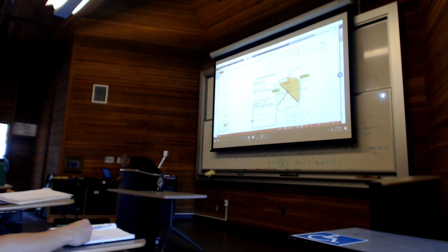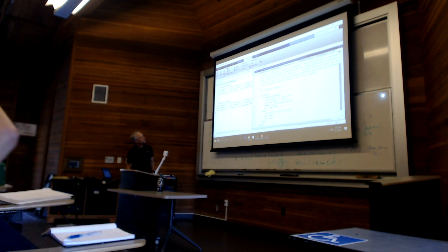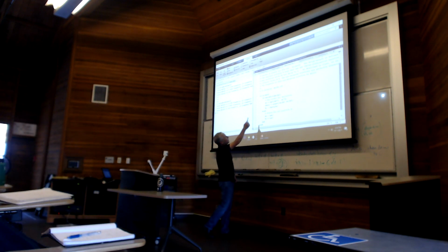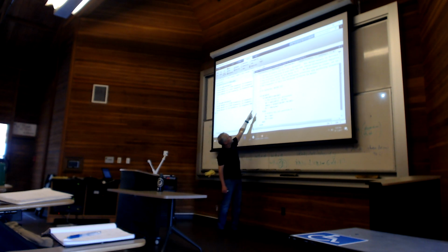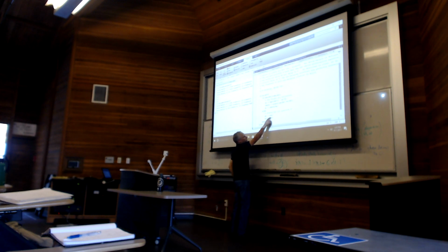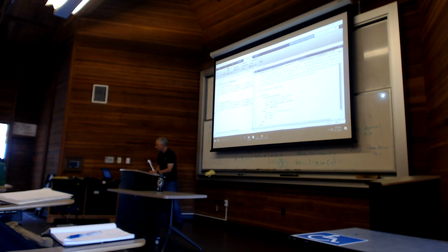So the code is delay margin calc. It's posted for you. We give it A1 and A2. I check if the absolute value condition fails, fine. Otherwise we'll print an error that says system is not stable at t equals 0. If A2 is greater than A1, like we're supposed to, we calculate omega, we calculate the arctan 2, and we calculate the time delay. Otherwise, if that if statement is not true, we know we're stable for all positive t, so we'll return an infinity for this time delay margin, and no frequency causes a problem. So that's the code, very simple to use.